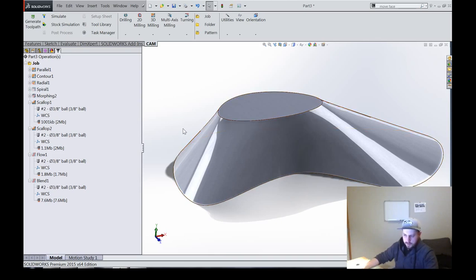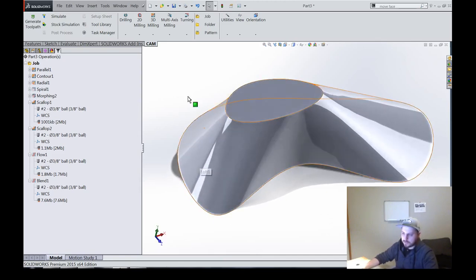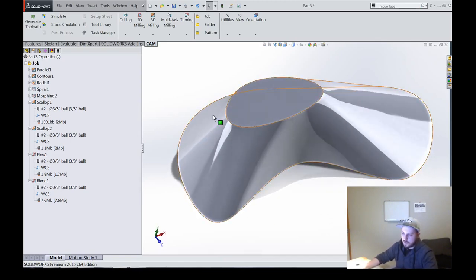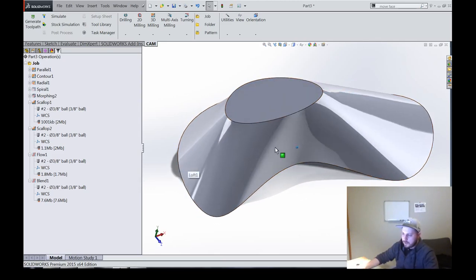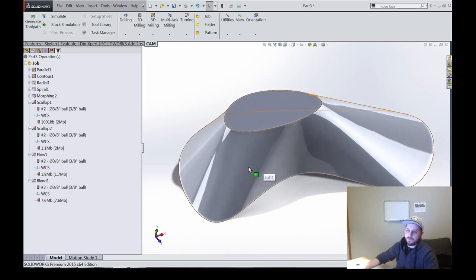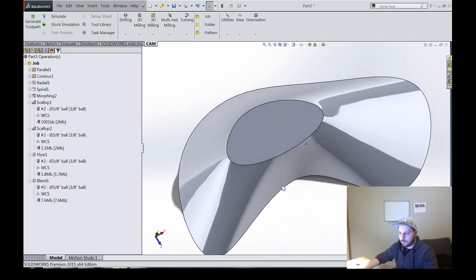Or even on a single surface, they might not go the direction you want because the surface was made in some funky way and isn't representative of the curvature, which is an odder use case. The other is way more common. The long and the short of it is, if the UV vectors aren't doing what you want the toolpath to do, you can't use Flow. It's going to fail on you, and you have basically no control over it.